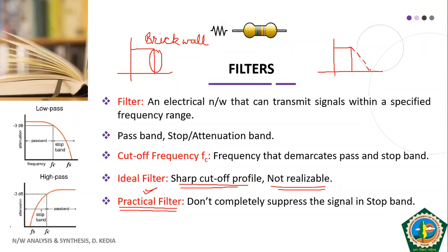Okay, so it will not come to zero at once, it will come down gradually like this. Now you see in the figure clearly the orange line, it shows the gradual change in the pass band of the filter. In the pass band of this low pass filter, certain frequencies are also being passed by the filter.